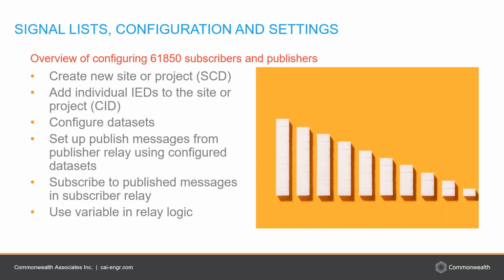There are some manufacturers that have standard data sets that they provide with the relay. Others allow you to do whatever you would like. Those that provide them still have the capability to do whatever you'd like, so that's not a restriction, but you have something to start from in some cases. So these data sets could be information for breaker failure initiate and breaker failure tripping. You might send similar information within the same data set.